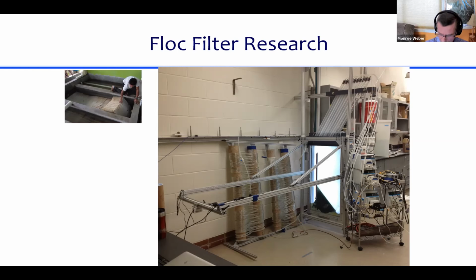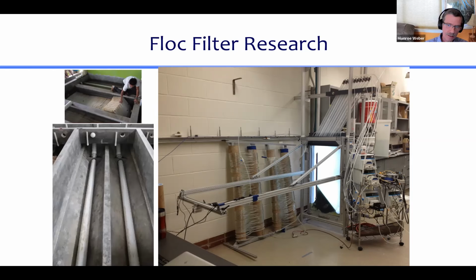And so what we did is we looked at our sedimentation tanks and we realized if we could take one little slice of a sedimentation tank from Honduras, that's half the width of a sedimentation tank, and bring it into the lab, so there it goes, 2,000 miles from Honduras to the lab. And then if we make it not 6 meters long like we do in Honduras, but, sorry, switch to metric, 1.25 centimeters.